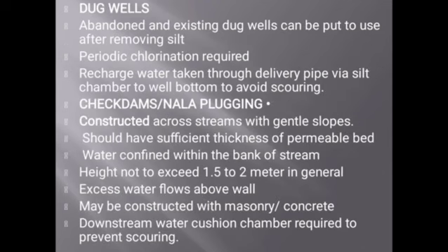Next one, dug well. Abandoned and existing dug wells can be put to use after removing silt. Periodic chlorination is required. Recharge water is taken through a delivery pipe via a silt chamber to the well bottom to avoid scouring.